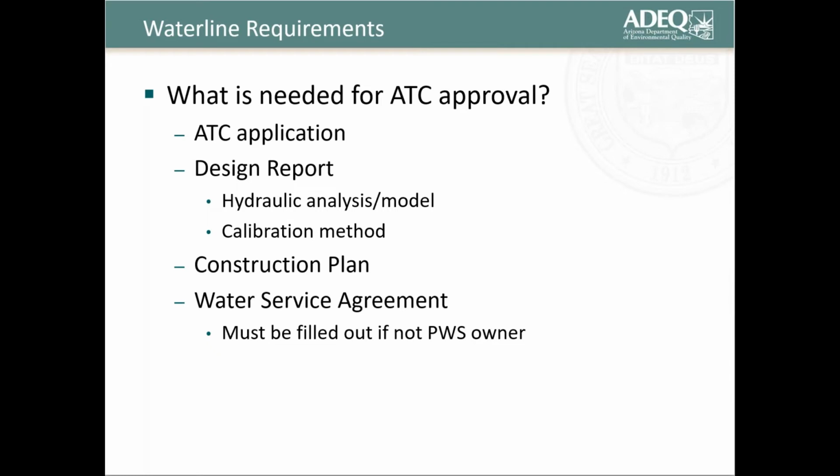Another deficiency is usually that the hydraulic analysis is not calibrated. Sometimes it's just run based on a given demand flow that was taken from the public water system, and then a hydraulic analysis is used. But we like to see that it's verified through a fire flow test or any other kind of calibration method.